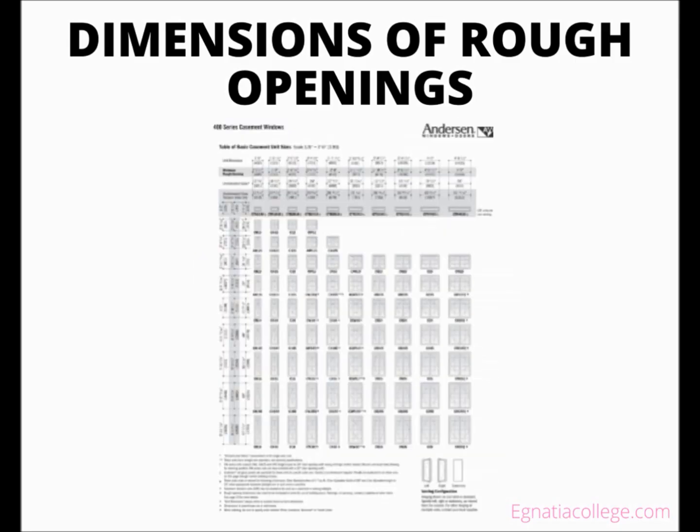The rough opening dimensions are not usually given on the drawings. They should be obtained from the manufacturer. Window manufacturers do not list the same size information in their literature, but they do list the rough opening size. Other sizes they sometimes list are nominal size or unit dimensions, approximate overall size of the window, and glass size, size of the actual glass in the window.